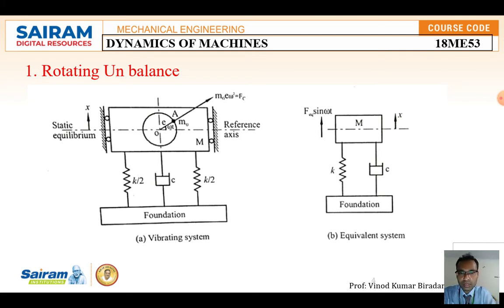So this is about here; I have given one example. A mechanical device is going to be fixed on this foundation. This is what is inside: the unbalanced masses. If you start it, there is a chance of producing a centrifugal force, which is equal to m naught e omega square. That is called the centrifugal force.